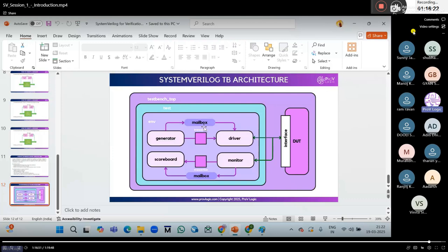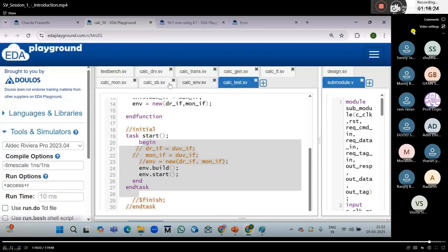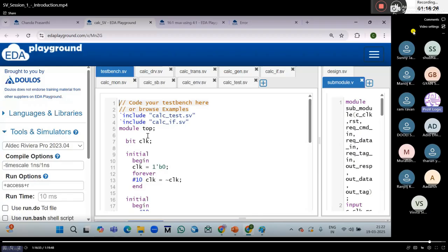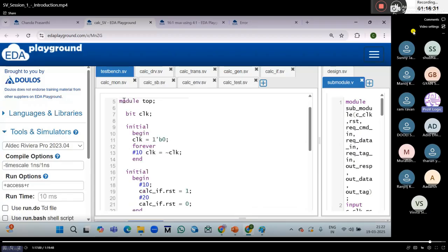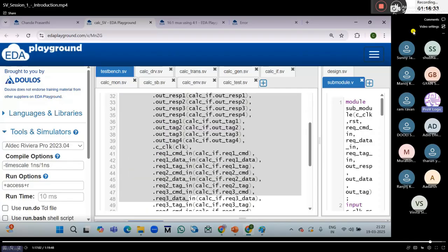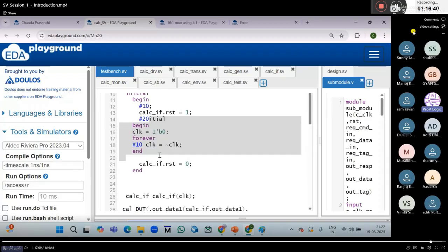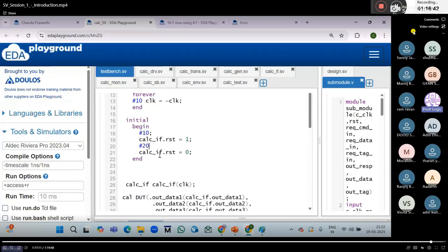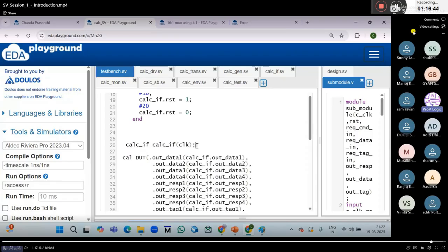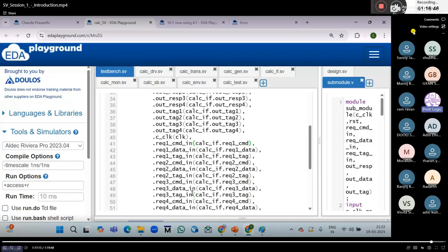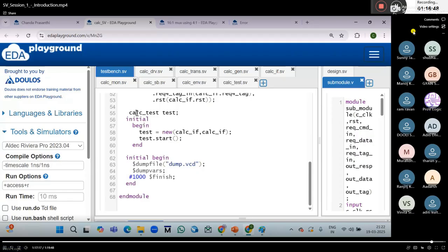So in the test bench top, the tester and interface are both included here, and this is like the main Verilog test bench. However, we connect the main Verilog test bench like generating the clock, instantiating the clock, data, reset, and DUT interface and main DUT signals, same as a normal Verilog program. And the $dumpfile, the main test is called from here.